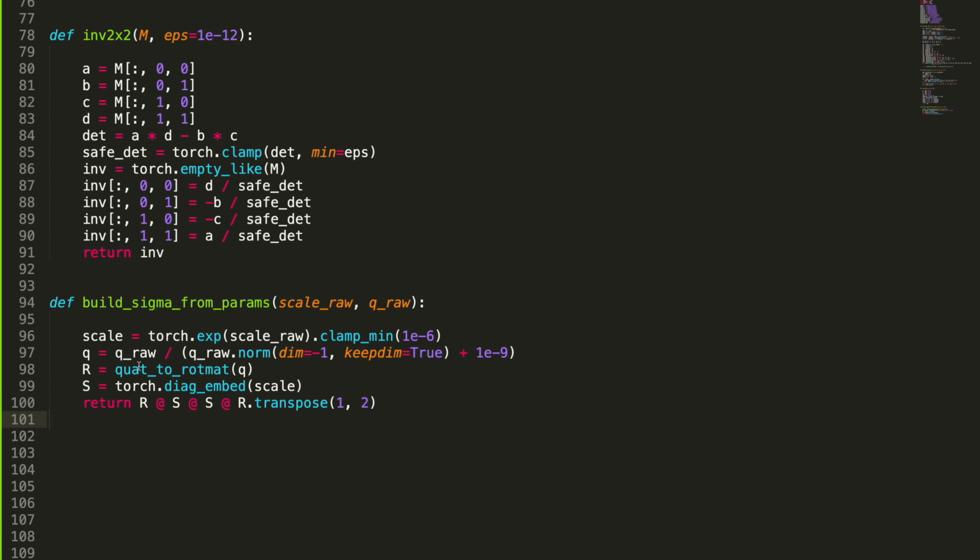And you can see that we need to convert the quaternion to a rotation matrix. So we're going to do that in the next function. A rotation matrix is a 3 by 3 or a 4 by 4 matrix, and it's over-parameterized. There are some redundant values in the rotation matrix, so you could just summarize it with 4 values, and that's what the quaternion is doing.